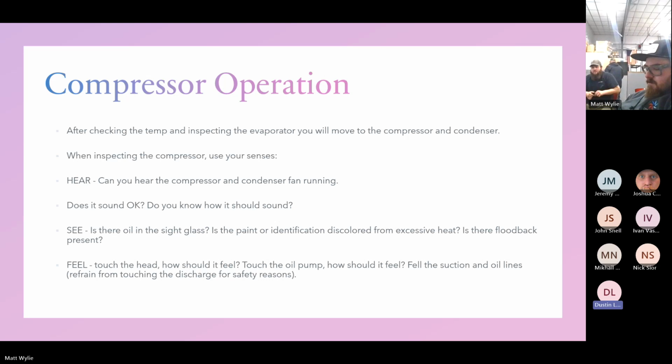Move L1 to L2 and L2 to L1, or L2 to L3 and L3 to L2. But whenever you're messing with 3-phase power and not single phase, always verify rotation and direction, whether you're replacing a motor or doing a new install. That's why startup and double checking our work after we complete something, whether it's an install or a service call, is important, especially with 3-phase power, to make sure our directions are correct.